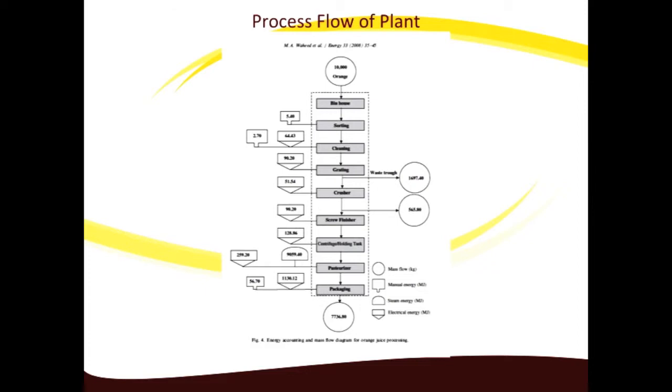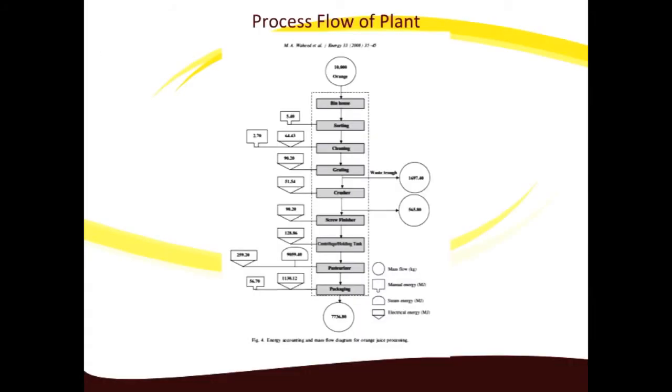The high exergy destruction in the pasteurizer may be reduced by an increase in the capacity of the holding tank, which will result in the reduction of the load on the boiler. Another way to reduce the high exergy destruction in the pasteurizer is by the introduction of heat integration between the pasteurizer and the packaging units. Heat integration for minimum utilities consumption corresponds to minimum production of entropy as well as to minimum ideal work given by the process utility stream.